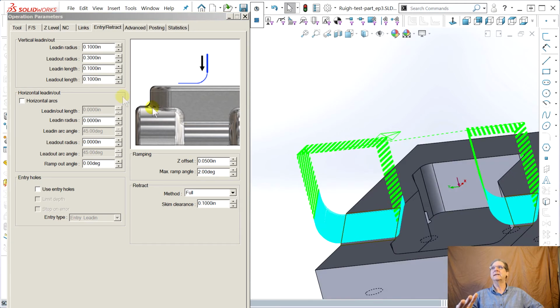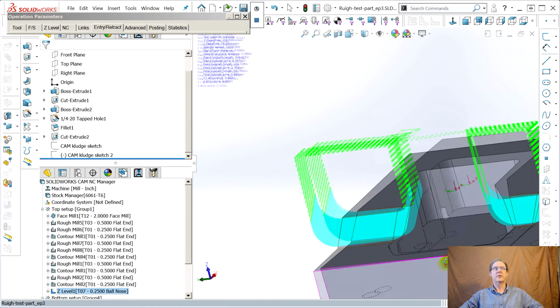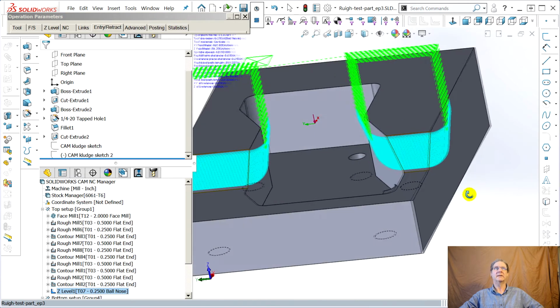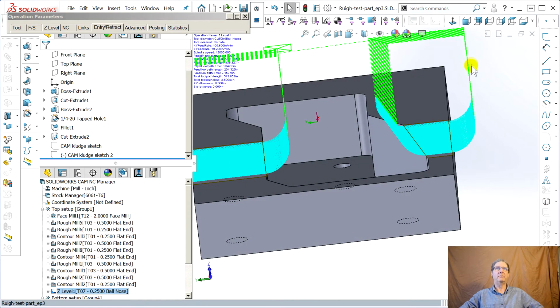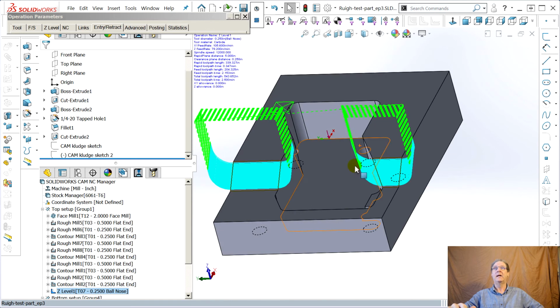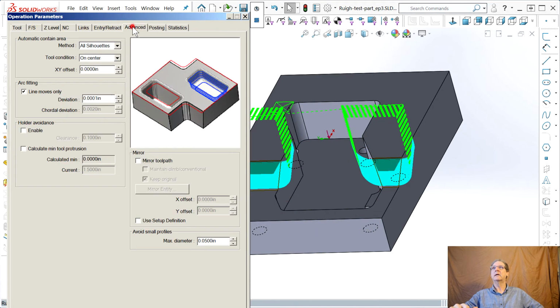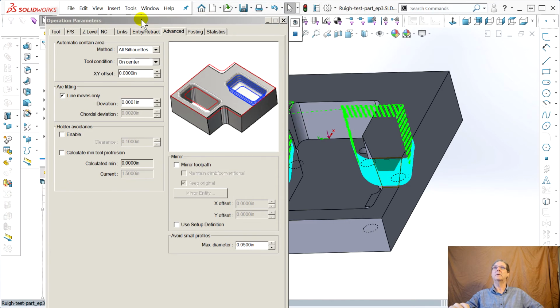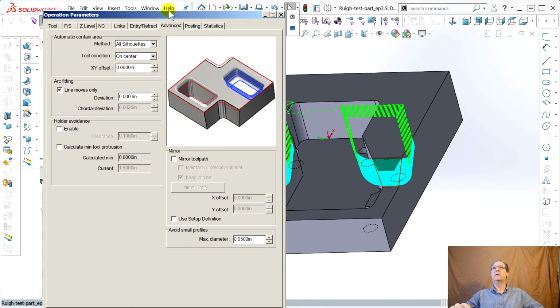It turned out, I said, the other way to solve this is just make the lead in radius 0.3 as well. Preview. So now when that ball mill comes down, it's down without hitting material, and then it goes across. And it's only going across a 5,000 step, so I'm not worried about any kind of problems with that. So now you click, click, click. Oh, some tabs open, some won't. Okay. Now don't hit this like I always do and forget.